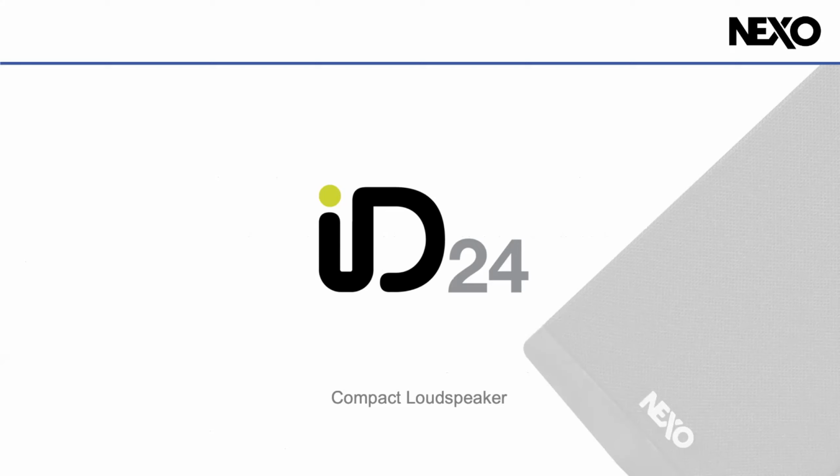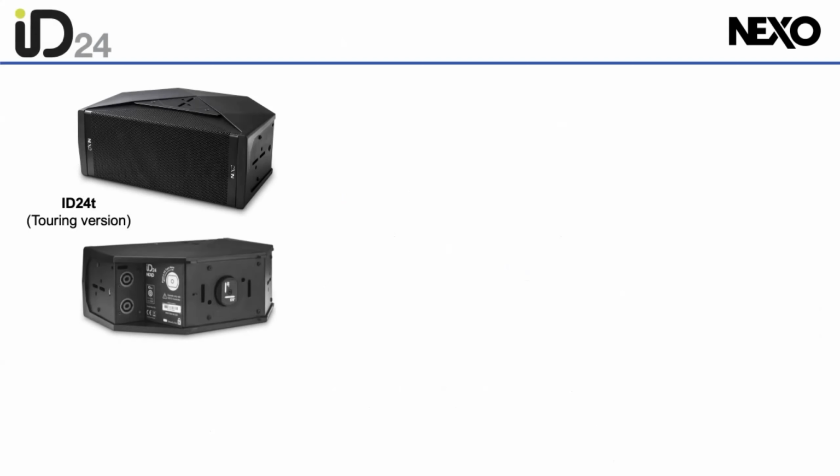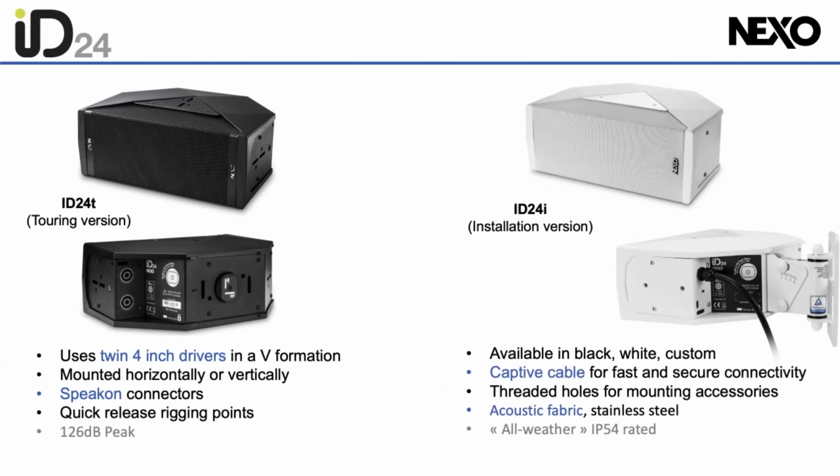The ID24. This is going to be the dual driver variation. This is what originally launched with the ID series lineup several years back. There is, again, a touring and an install version. These are twin 4-inch drivers in a V formation. The big differences between the install and touring version are the grill covering, again consistent with the ID84, and a captive cable gland versus an NL4 cable. 126 dB peak on these, extremely high output.